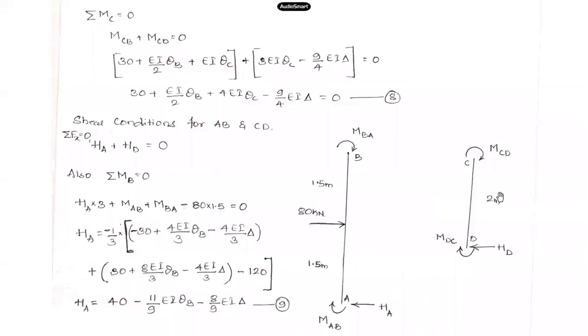So no force is being applied on this member, but D was fixed. There you come across this horizontal reaction, HD, and also you'll have member moments at joint C and joint D. Here MCD is taken to be in clockwise direction, MDC also is taken in clockwise direction. I'm not worried about this direction. I've just taken all the moments in clockwise direction at this point. Later we'll come to know on the basis of sign what the directions are.